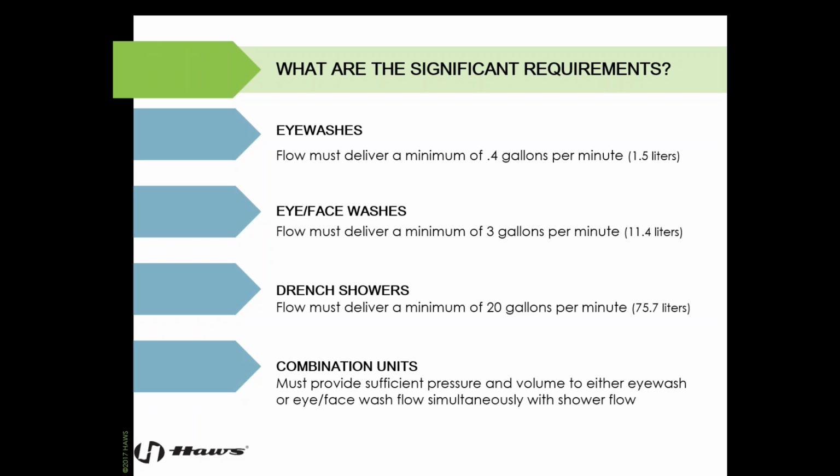So all of these are required a minimum of 30 psi. In the standard, there isn't a max, so anything over 90 psi could blow out any flow controls that may be in the heads of the equipment, the head of the eye washer and the head of the drench shower, so keep that in mind.